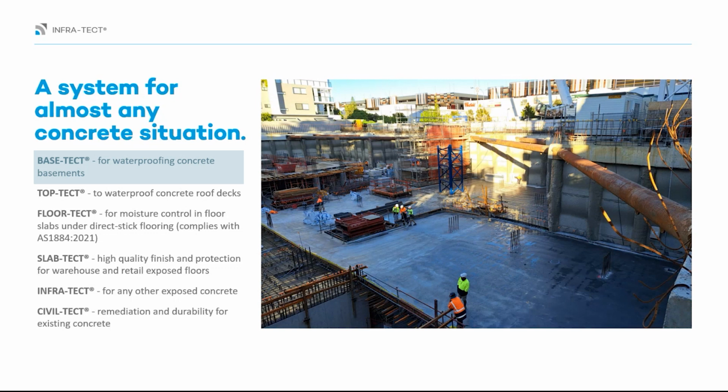Yeah, so it does relate really well. And it's a bit more of a systematic approach with construction joints and things as well. Exactly. TopTech system is essentially a very similar system to our BaseTech system. It allows you to waterproof a concrete roof using just the concrete alone. We do use that in conjunction with a lot of traditional membrane type things and drainage points as well. So that's becoming quite popular around here. I've got quite a lot of projects at the moment that are incorporating this system.